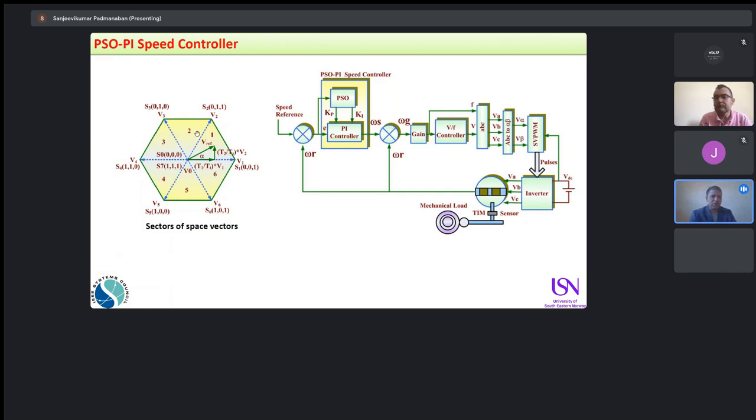Because in space vector modulation, we are working on 360 degrees of modulation, and every 60 degrees is shown here. For example, if I am here to control the motor inverters, I will be triggering in this triangle clockwise or anti-clockwise. This freedom is available in space vector modulation, whereas in other simplified modulations these controls are not available, so the power quality and the total harmonic distortion cannot be controlled in conventional modulation methods. So space vector is widely used in all the companies as well as for real-time application.